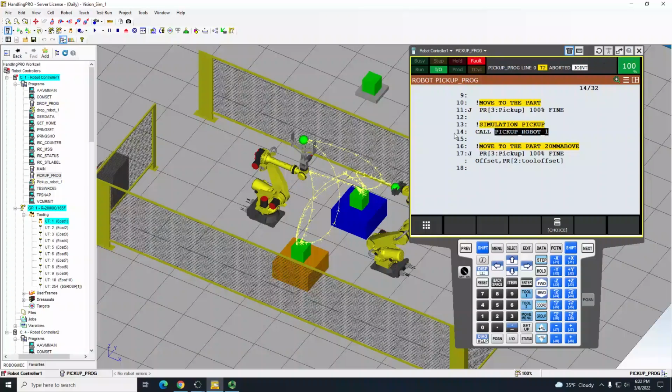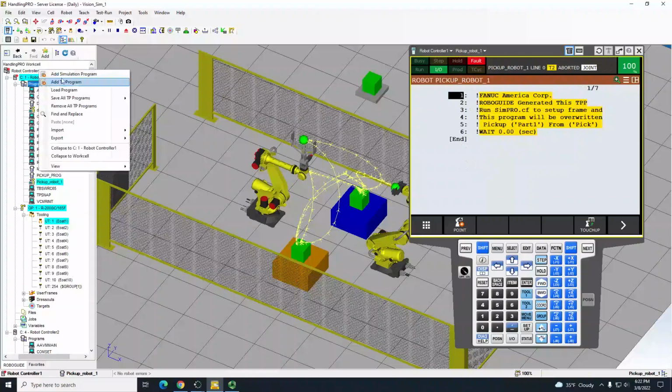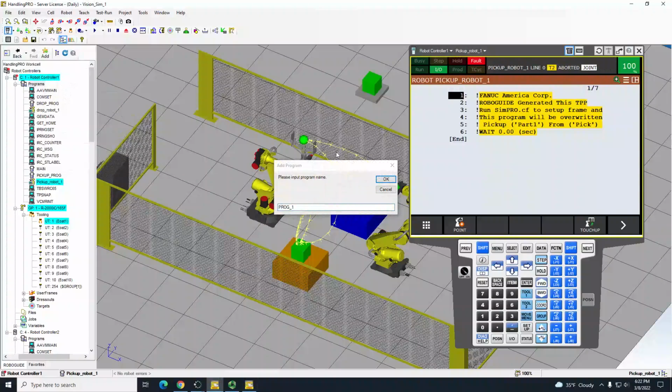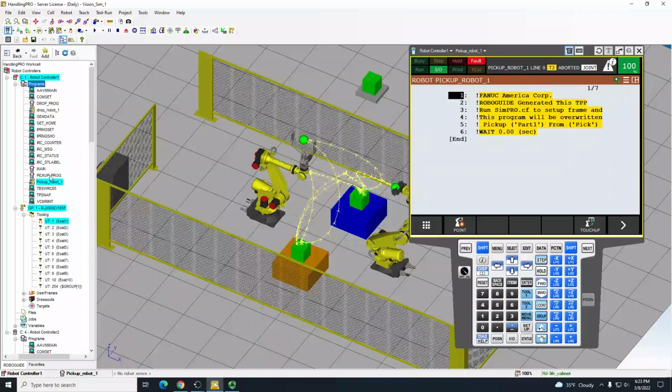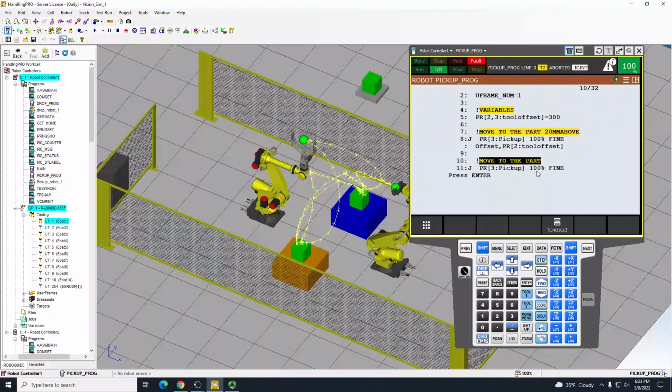So I was talking about the DO. In Roboguide, you cannot put on a DO directly, just like that. This is a simulation, so it works on all geometry. For picking up the part, like a DO, a vacuum suction turning on, or a gripper closing itself to hold the part tightly, what we do is create a simulation program. We create a simulation program just for that one line of code. Nothing else. Please understand, there is nothing else in that. It's just one line of code.